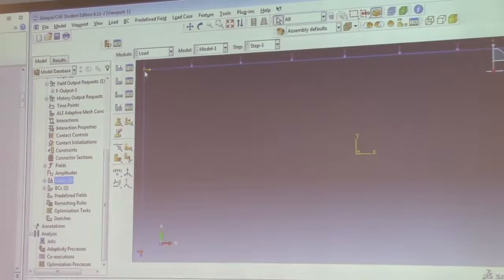No. For the truss problem, because a truss doesn't have a rotational degree of freedom, if you have a node on the truss, there's no way you can control this rotation. That's why in the truss problem, we cannot use many elements on one truss. You can only use one element per truss. But because beams have rotational degrees of freedom, this element type is designed in a way that it can control this rotation. So it will not collapse, don't worry about that.